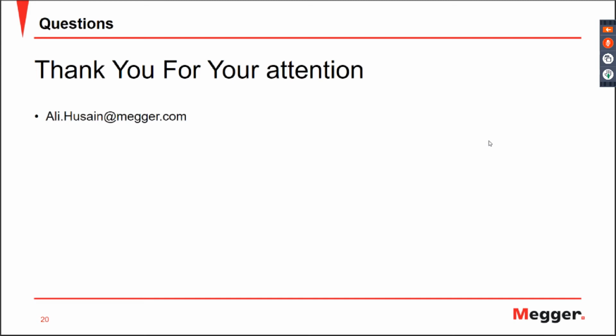Another question I'm having here is what is the effect of CT error in the stability of the differential relay? That's a very good question. Thank you very much for asking that. The CT error or protection CTs usually during fault will have a normal error of 5% or 10% maybe. Now, this error, when I'm having a through fault, meaning a fault not inside my transformer, but alongside my system, maybe an adjacent transmission line or